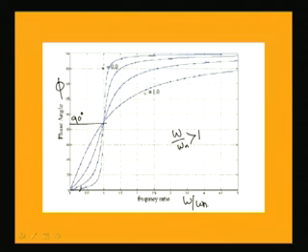So, irrespective of the value of zeta, all the systems will have a phase angle of 90 degrees when omega equals omega n, or omega by omega n equal to 1, phi tends to 90 degrees. And when omega by omega n is much greater than 1, you may observe that for low damping it tends to 180 degrees, and with an increase in damping this value decreases.